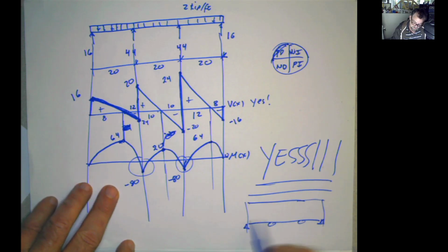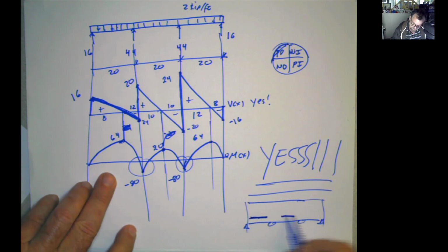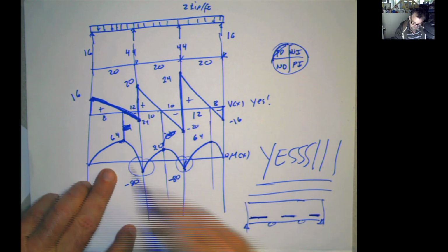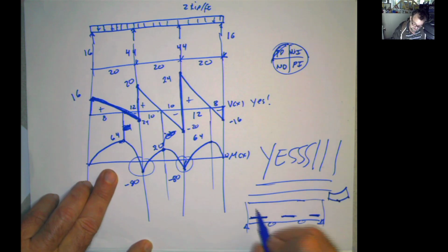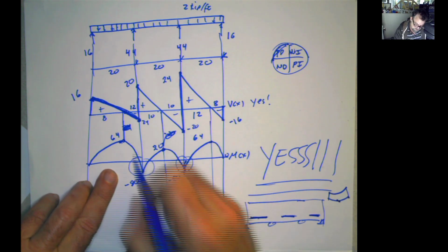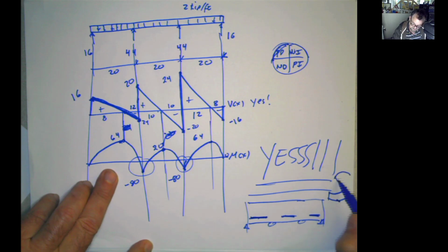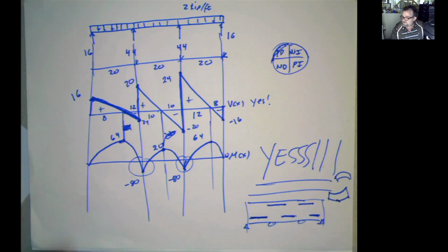Whenever you are in between these two, the majority, I'm not saying that this is going to be cut like that, the steel is going to be continuous, but here, here, and here at the bottom, you're going to require more steel because this is the tension. That's why you have the steel at the bottom. Now, in the supports, you can see that the moment is negative. The moment is like that, so the tension is going to be in the top. That's why when you have a negative moment, you have to reinforce this part here on the top. But this is just an extremely simplified analysis.